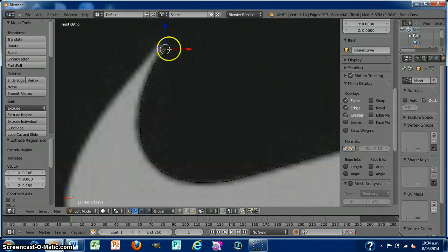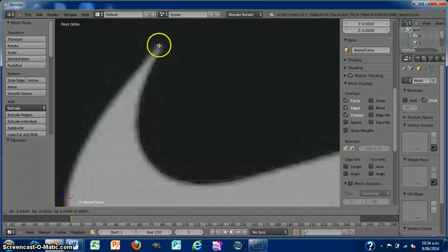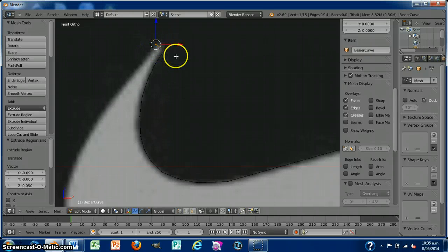Now, one thing we've learnt before we go any further, with the 3D printer, it doesn't really like to print sharp corners like that, or sharp edges. So what we need to do at the end of our tick is to give it a little bit of an edge like that. Now I'll bring it down this side.